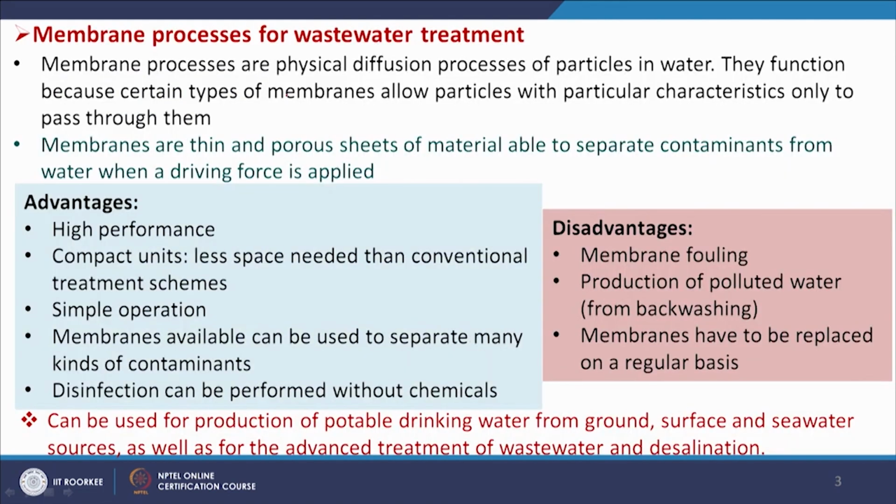The membrane processes are physical diffusion processes of particles in water. They function because certain types of membranes allow only particles with particular characteristics to pass through them, and membranes are thin and porous sheets of material able to separate contaminants from water when a driving force is applied.